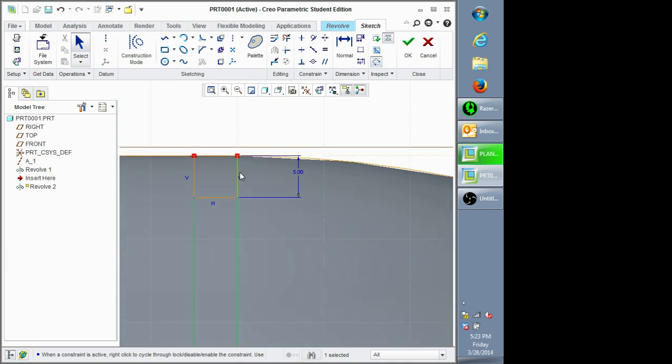Since I'm making them the same dimension, we can actually set up a constraint so that they're equal lengths. When you're drawing out the lines, there is an option that does appear with a constraint to do that. But it's very easy to lose that constraint, so I like to do it this way. Select the two lines that you want to make the same dimension.